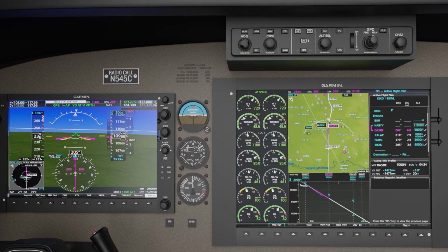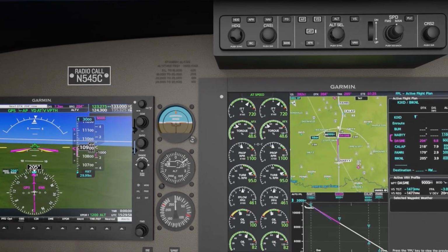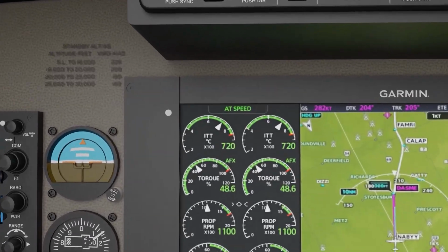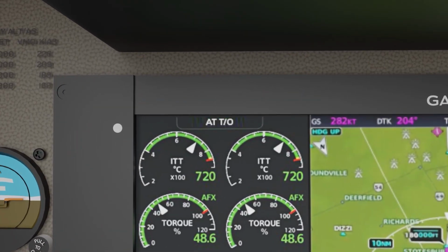To maintain mode awareness, you must know where to look. The autothrottle modes we're going to discuss will be displayed in the Autothrottle Mode Annunciator, located above the ITT gauges in the EIS pane. The status of the autothrottle is shown in the middle of the AFCS status box. The color philosophy for autothrottle modes is the same as the AFCS modes: green for active, white for armed, and yellow for abnormal modes or disconnects.